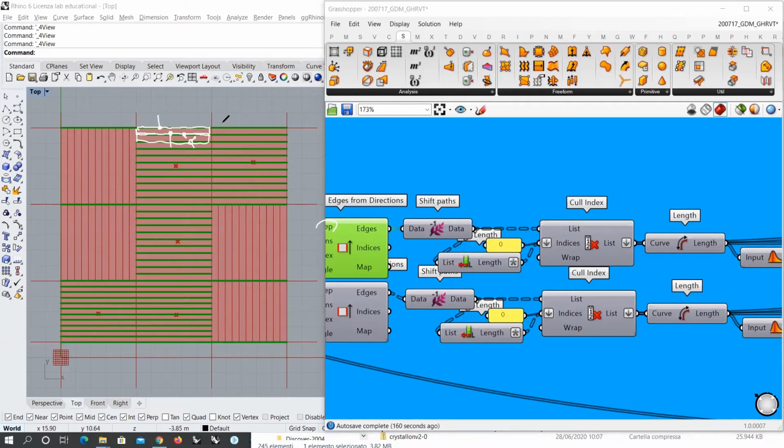Also, another thing, this edge here is not necessary for the secondary beams because this is actually the axis for the primary beam that we already have. So we don't want this line, we don't want this line here, and we don't want this line that belongs to the Y orientation. We don't want this one, okay? So we must get rid of this kind of elements.